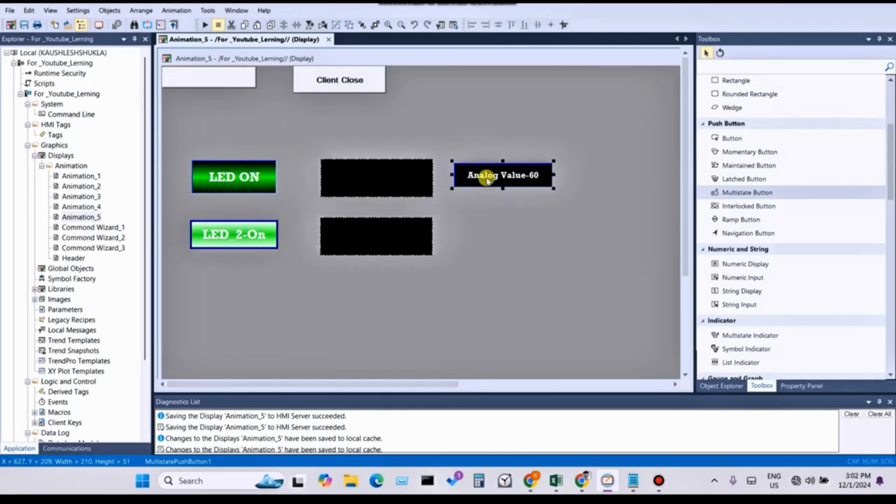And you can use this in logic. I will create a video with FactoryTalk View and FactoryTalk View Studio 5000, a combination of both. At that time I will show how to create an add-on, how to create a faceplate, how to link the add-on with the faceplate, how to do parameter passing, and how to link with and without parameter passing in the faceplate.